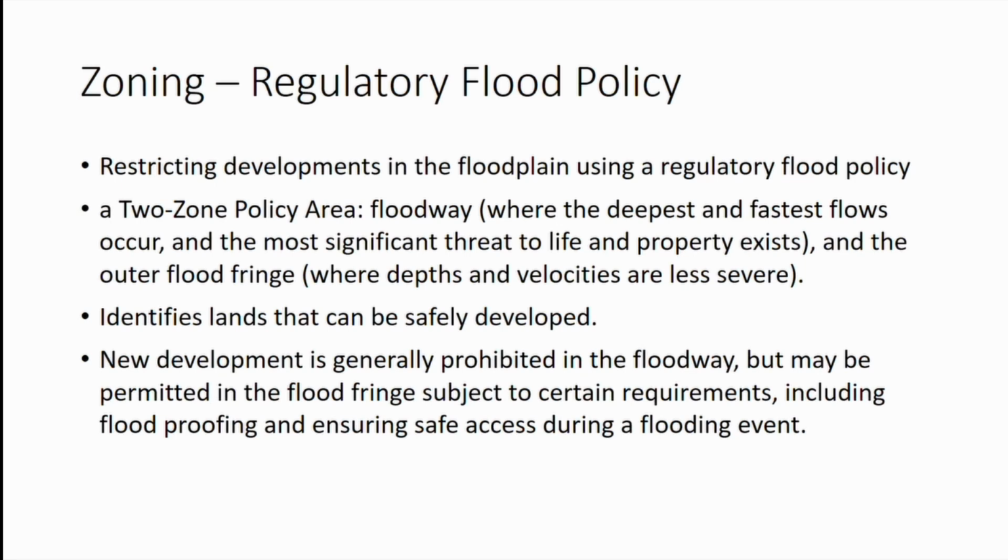And beyond that zone within the floodplain, we allow development, but with the caveat that such development, whether houses or industries, ought to be flood-proofed. What that means is that you don't just develop right off the ground, but you elevate a bit above the ground with structures before you build, such that in the event of flood, a house is not flooded.